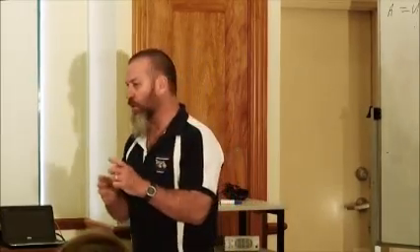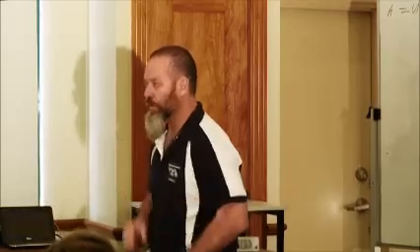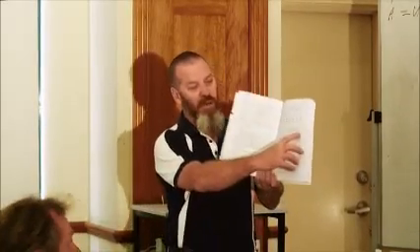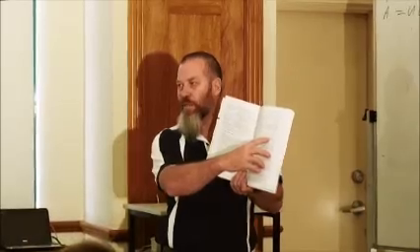That's a stick roof. If you have a look at that second diagram on the right-hand side, think about what I said about connections and not spacings. If you have a look at this one here, this rafter is connected at the top plate and its next connection is where it meets the underpurlin. Can you see that?